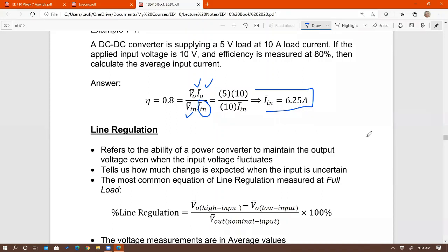Okay, so before you design a buck converter, for example, you would have to know what kind of output power this buck delivers max. So then you will find out, okay, it's going to be 100 watts. Based on that, and then at what output voltage, right? Besides output power max, also output voltage. Let's say the output voltage is 5 volts.